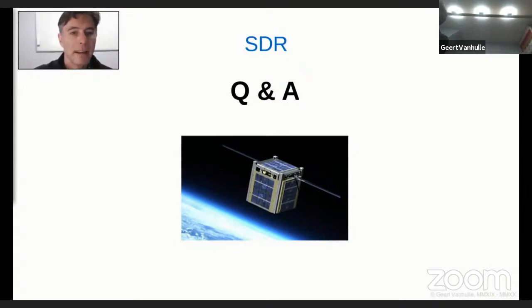So we will add a digital inverse signal of the same amplitude but inverse phase digitally to our sample stream that will compensate for the harmonic that would appear normally at the output of the DA converter. So this way you can filter this harmonic on the outside, you can filter this analog problem at the output in a digital way before the signal leaves the digital stage. So this is a huge advantage, of course, especially when you have stuff that is already in space.